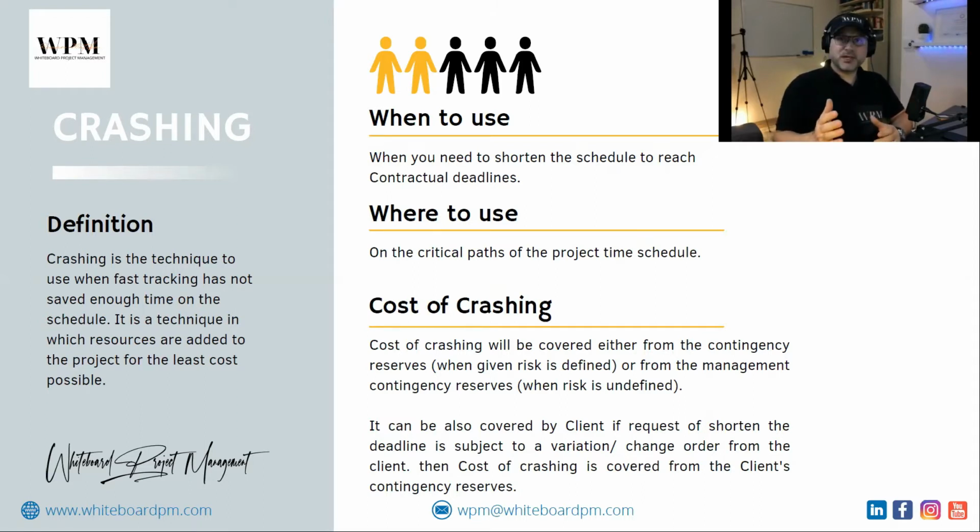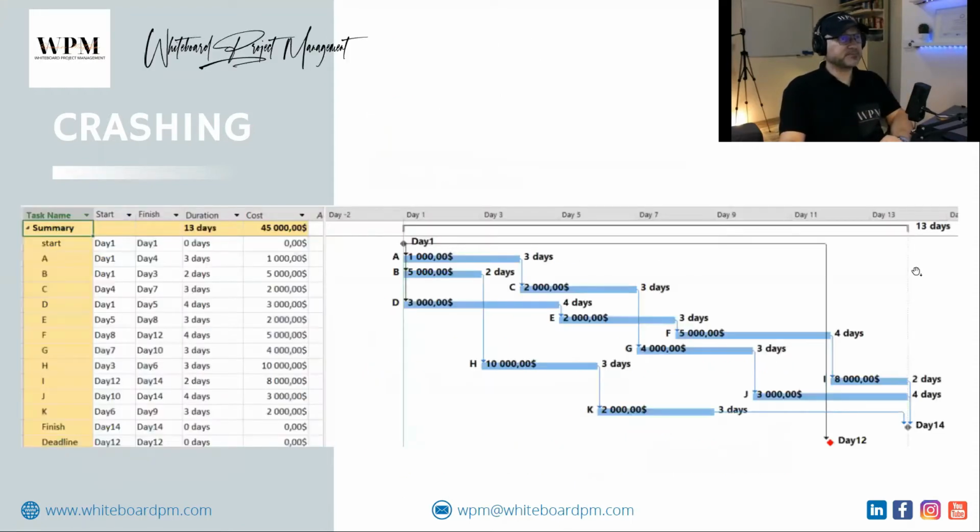If you are a contractor and you received a change order from your customer, that means the cost of this crashing will be covered by the customer in a change order. And this will be paid for you either as a lump sum or a cost plus fee. It's according to the agreement between you as a contractor and the customer. So this is the cost of crashing. Now,